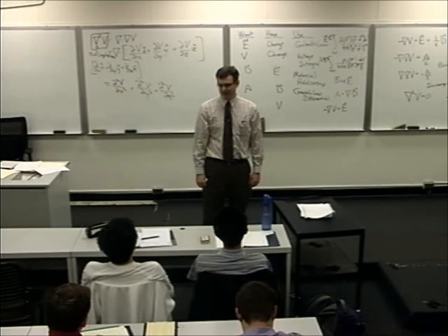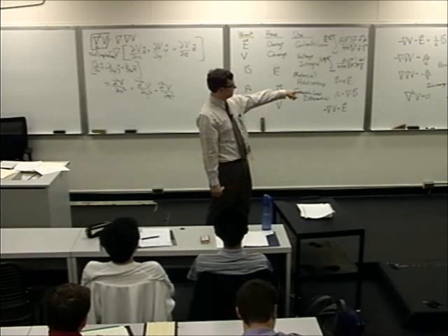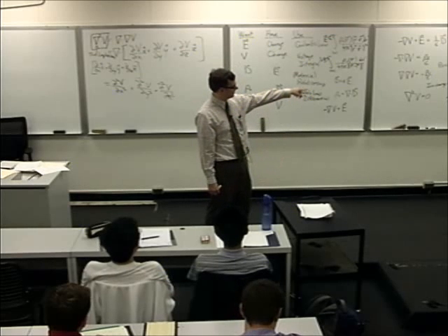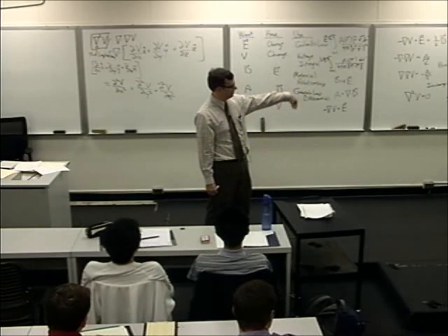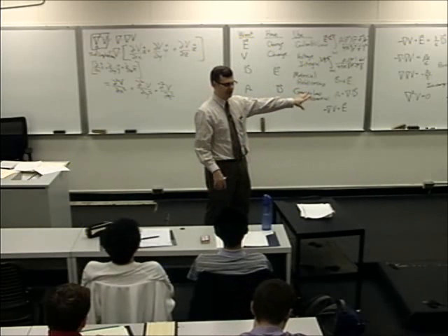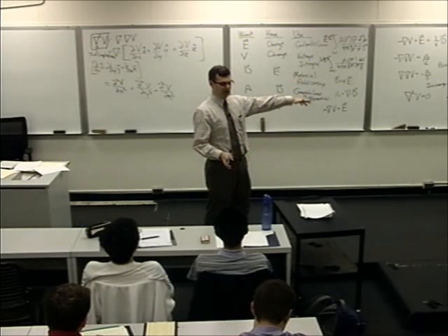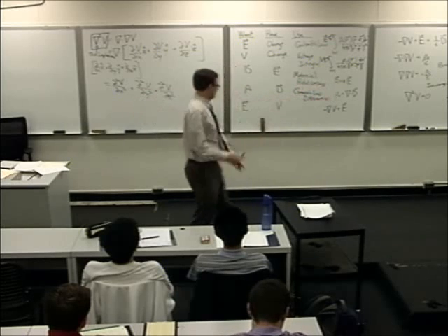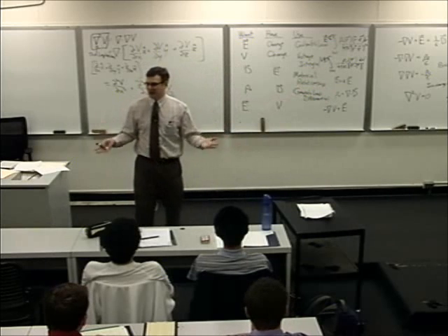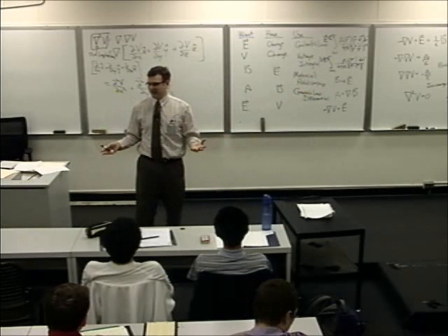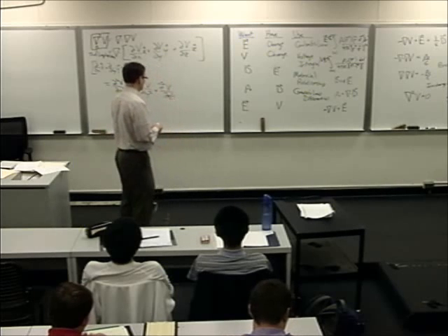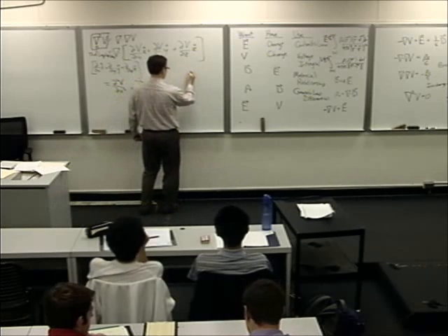Two solid semesters. We were doing finite element analysis, which is really similar to the thing that I drew over there, except instead of using square grids, you use triangular grids. And it turns out you can actually formulate a way to solve that problem in any kind of coordinate system. So why on earth would you ever try to complicate your life by discretizing something other than a grid? So, let's say I had this boundary value problem.